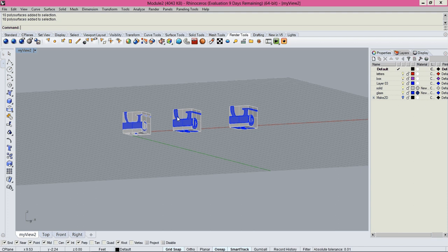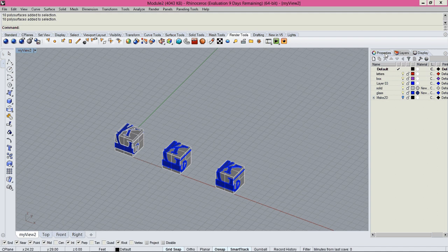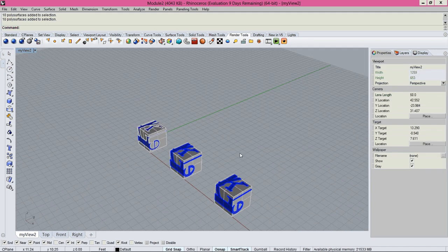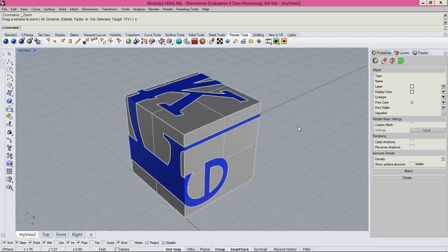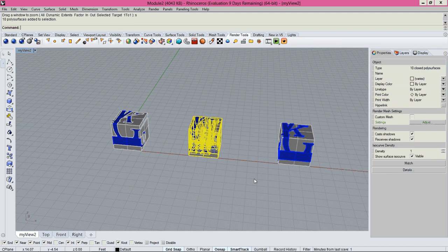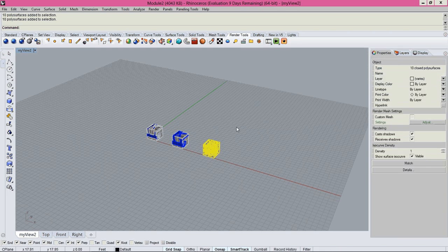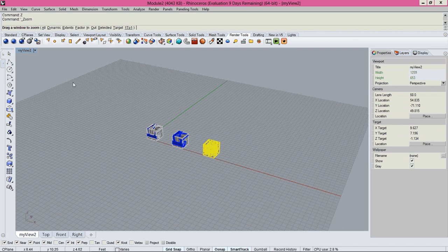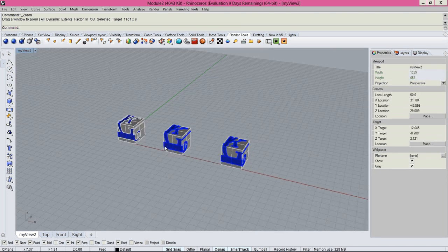If you guys don't like to work with a parallel view, which is the one we have, you can always just deselect everything and go to properties and just go back to perspective. We're gonna go back to parallel afterwards, so it's fine. Okay, we have 3 boxes, 1, 2, 3. By the way, sometimes if I'm far away, you can select some things and say C, you see there, enter, and then you can say selection, sorry, S, enter, you go to that, so yeah, now you move around that object. Okay, anyway, go to the point.